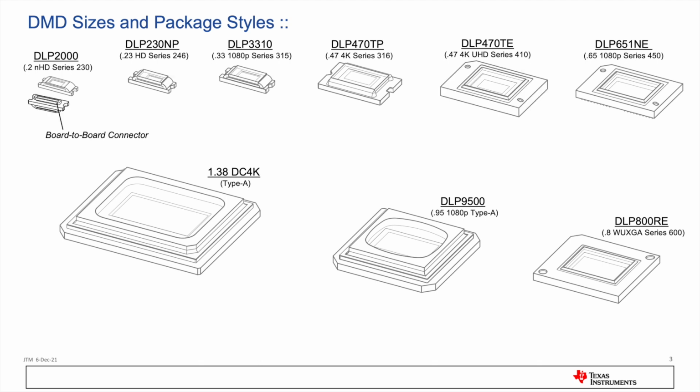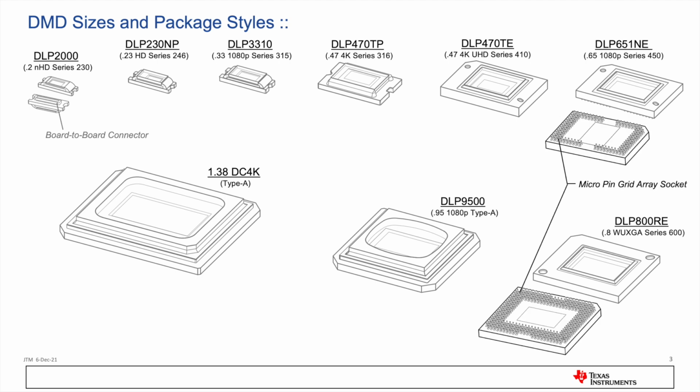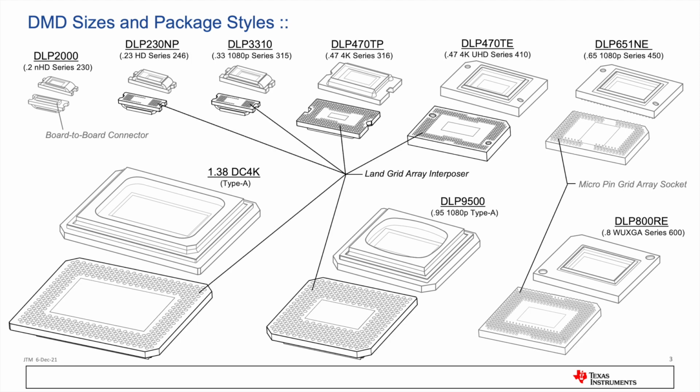DMDs with board-to-board connectors utilize board-to-board connectors in the system also. DMDs with micro pin grid arrays utilize sockets. And DMDs with land grid arrays utilize interposers. DMDs do not utilize industry standard packages, and as a result, all except the board-to-board connectors are a custom design.